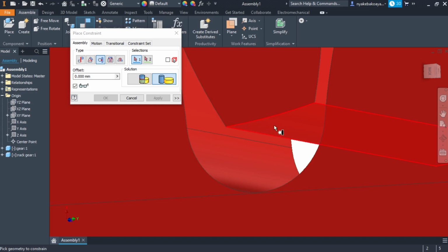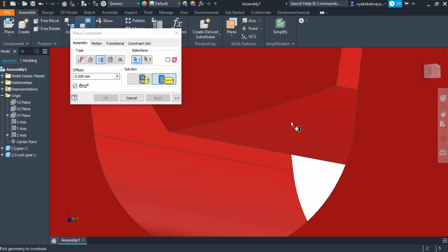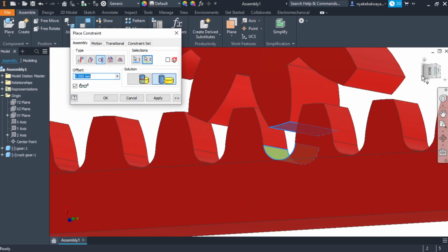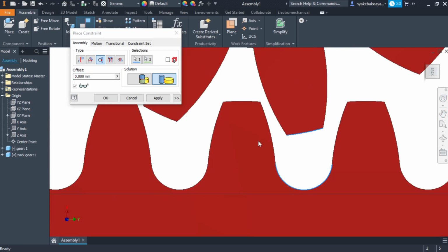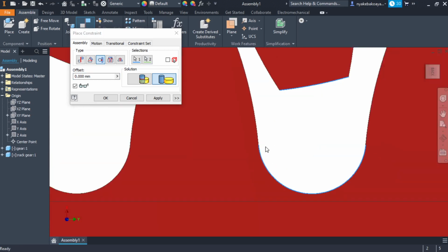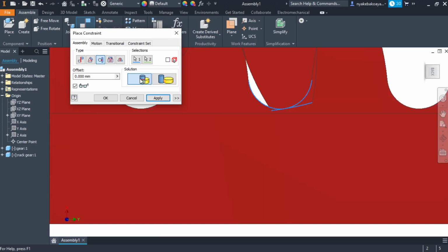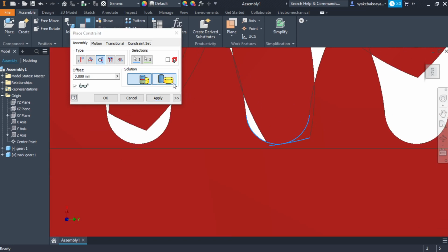If I select this bottom curved surface that is highlighted in red there, and click this curved surface there, it's going to make those two tangents. And I know now it doesn't really look like tangent, but generally that's it. We have two types: the inside tangent like that, and then we have the outside.